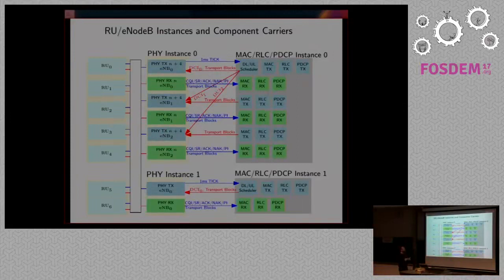Now, we can further subdivide this into what we're calling instances. A radio or a physical layer instance could be several equivalent base stations inside, and I'll show you a picture of why you would want to do that. One very clear example, these could be 3 sectors of a big base station. They're independent protocol entities in some sense. Or they could be what you would call a virtual base station, if this is acting as an antenna array.